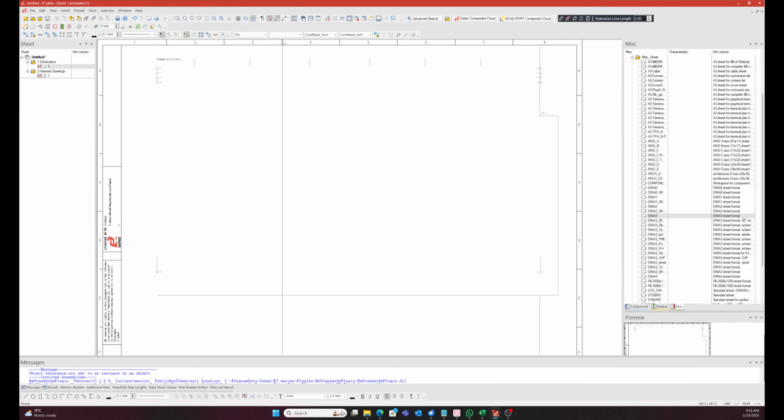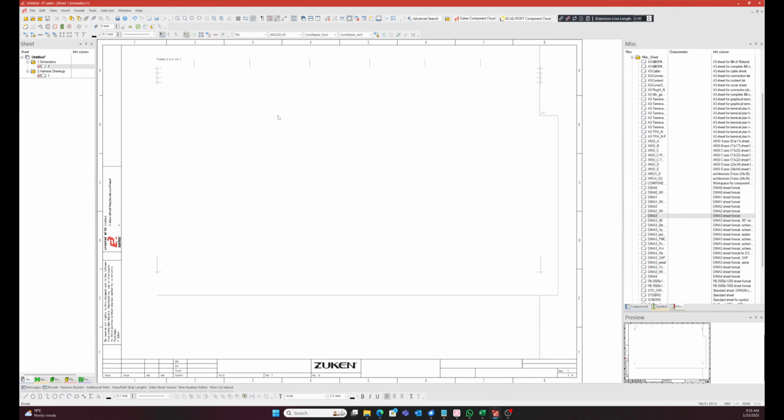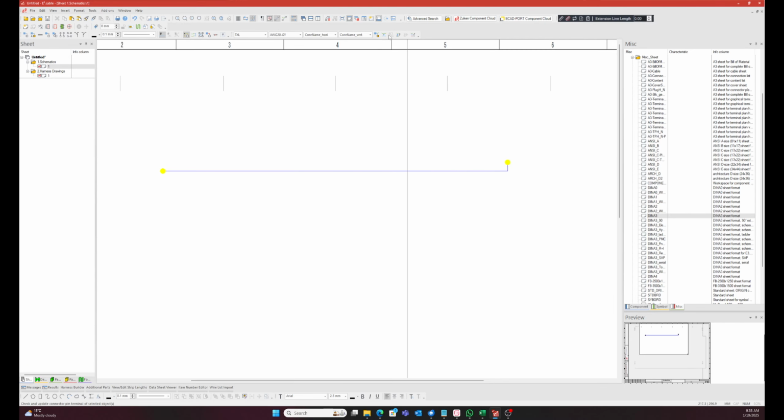So for argument's sake, I'm also going to change my default to front wire. That makes sense. Now from here, you can remove buttons and things like that. You can go into a lot of detail. One of the buttons I do recommend deleting for someone who's just starting to use E3 is this button here, generate signals. I've seen a lot of people use, instead of clicking this one, they'll click this one. And I'll show you what that is. But if I add a wire, let's just say here, I want to place another core number and they'll potentially hit this button here. I've seen people accidentally hit this button, thinking that's a text placeholder.